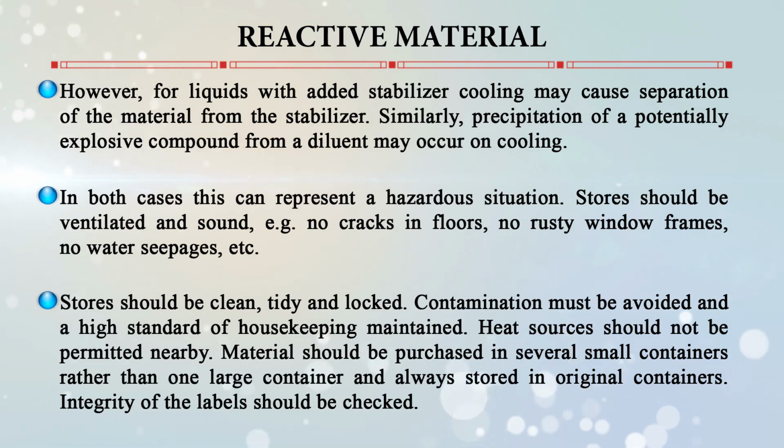Heat sources should not be permitted nearby, and materials should be purchased in several small containers rather than one large container, and always stored in original containers only, and the integrity of the labels should be checked. The use must be restricted to experienced workers only, and awareness of the hazards and the necessary precautions have to be maintained properly. The records of usage should be kept, and stock should be maintained on rotation, and old materials should be disposed of compulsorily